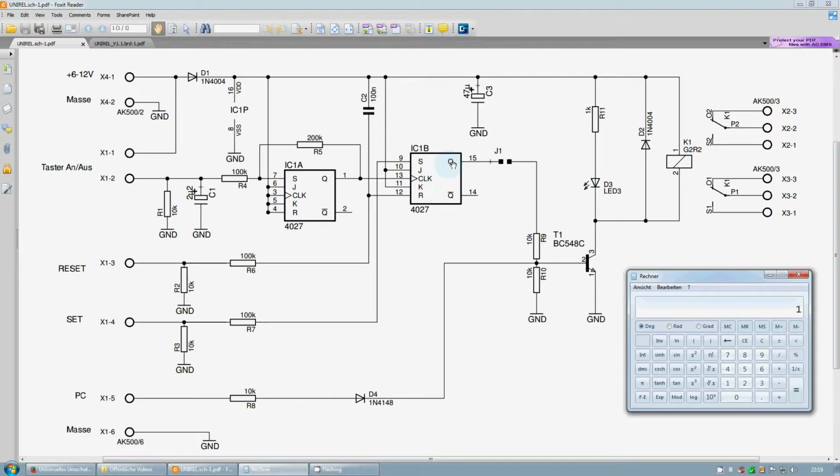Well, when it goes too high, it will also switch the transistor on, even if the PC input is low, because when it's low there can no current flow through to the base because of the reverse protection diode D4. So in the low state it will turn the transistor on in the same manner as a positive voltage here will do.